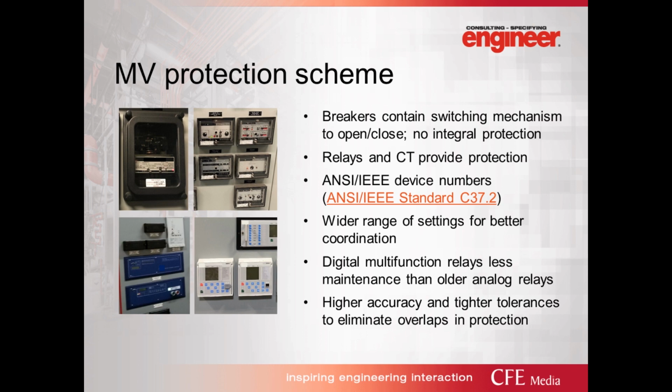A relay has a much wider range of settings, so they're much better for coordination. The 2 pictures at the top of this page are old analog relays. Each relay had its own individual function. It had dial gauges and things like that in the old analog world. The two at the bottom are digital relays. These are now multi-function relays, so they'll have the functions of several different relays built in.